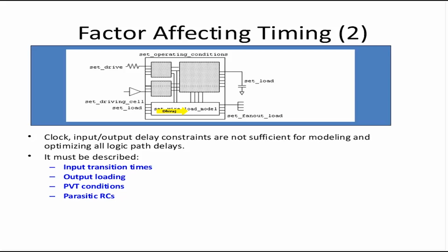Although there is something called a custom wire load model. So for a particular chip, your backend team or library team can come up with a custom wire load model, which is specific to your chip. This is again a separate topic altogether, but there is one such case, so you can use that custom wire load model. You use commands like set driving cell or set input transition. Don't worry about the set drive command. Set drive is not used extensively now. It's either set driving cell or set input transition at the input side.